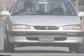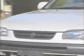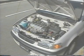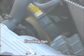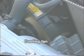To enable the radiator to radiate heat, large quantities of air must be led into the radiator to cool it. While the vehicle is running, the radiator is cooled by natural ventilation. While the vehicle is stopped, however, the cooling fan must be used to force air into the radiator. There are two types of cooling fan, the temperature-controlled fluid coupling type and the motor-driven type.